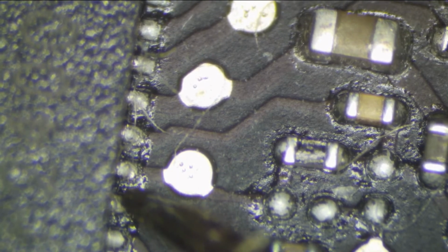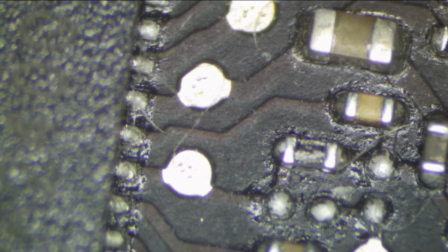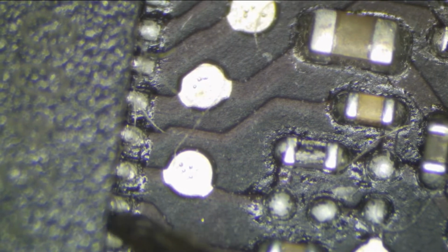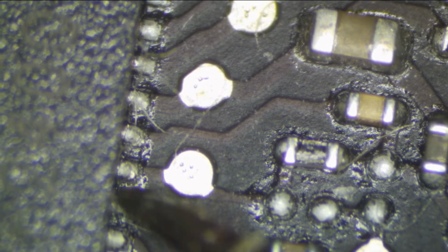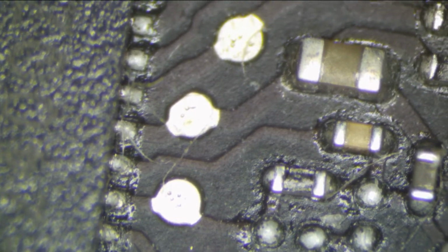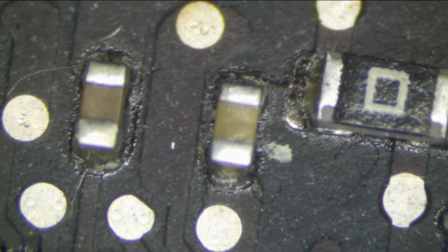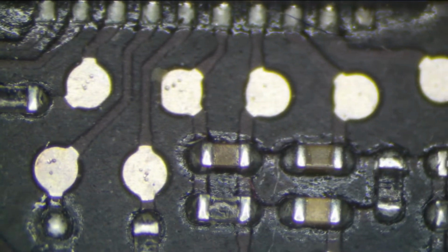So see this right here? So you can tell that, see that little chip there? That's actually a crack in the solder joint. That's present on here, here. And if we look close enough, the chip is actually not touching that. There's a break right there. So you can see right here, there's a few of them. That one's a little bit affected too. I'm sure it's going to be affected up here too. It's usually common on that top side as well as the bottom side.